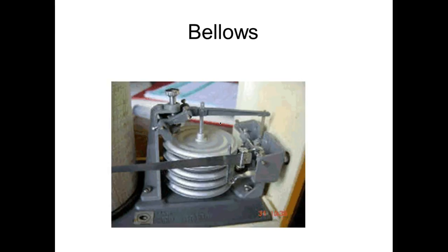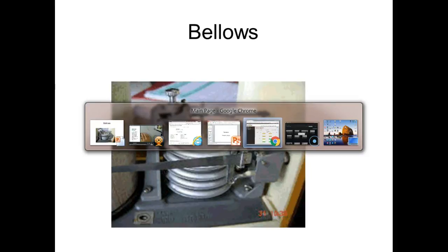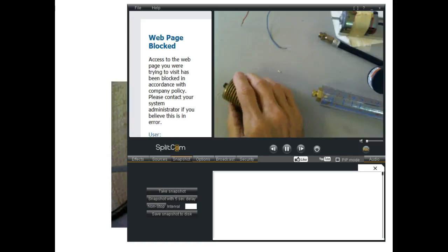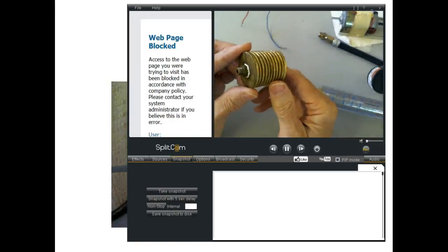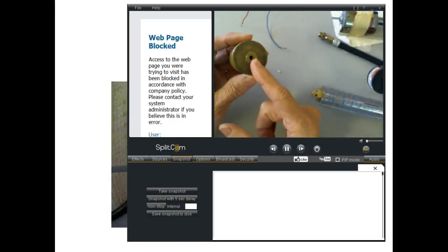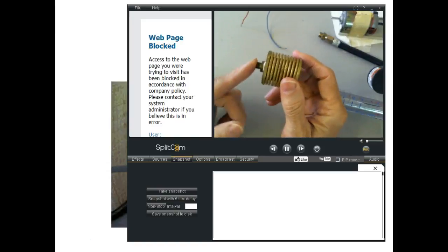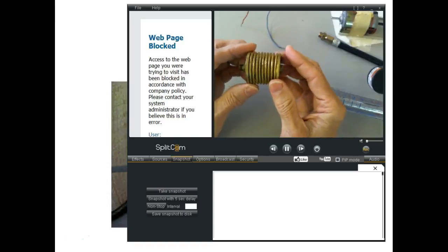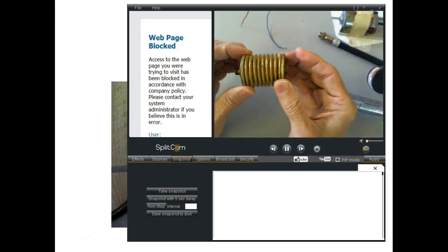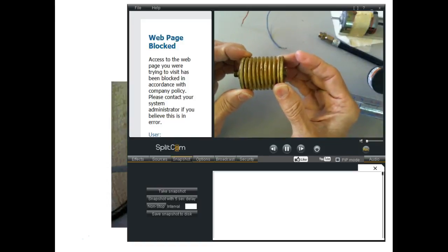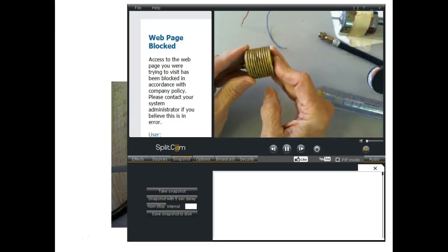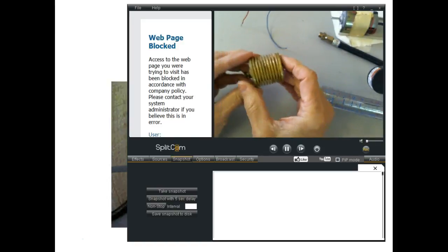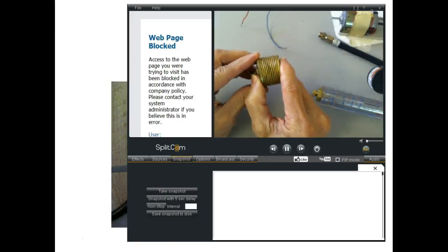Okay. So here's a bellows and an application. This is a bellows that I have right here. I'm not going to expand this out, guys, because you can see it pretty well. This is the end that mounts, and you can see it's threaded. We bring our pressure in right here, and what's nice, it can measure a vacuum. So if I put a vacuum in here, it's going to cause it to collapse.